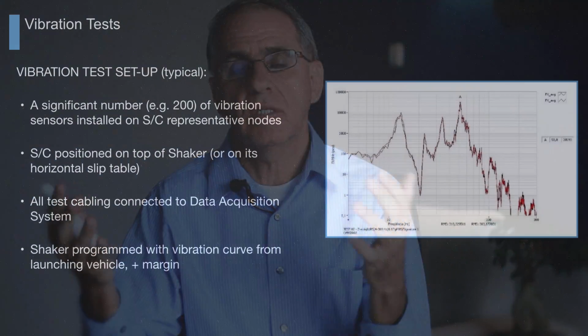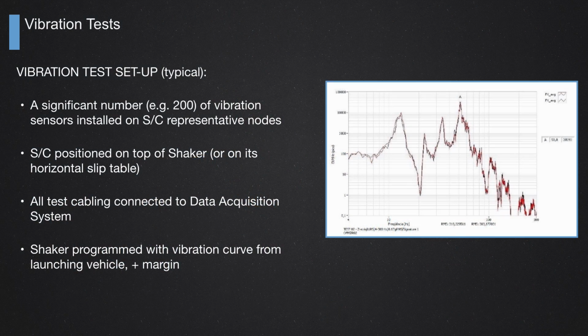So we put sensors in those points and they do the vibration, get data from those points, and then the design compares the real data that they get from the tests and the expected numbers of vibration they obtain from the modeling. They compare this to see if this is reasonable.